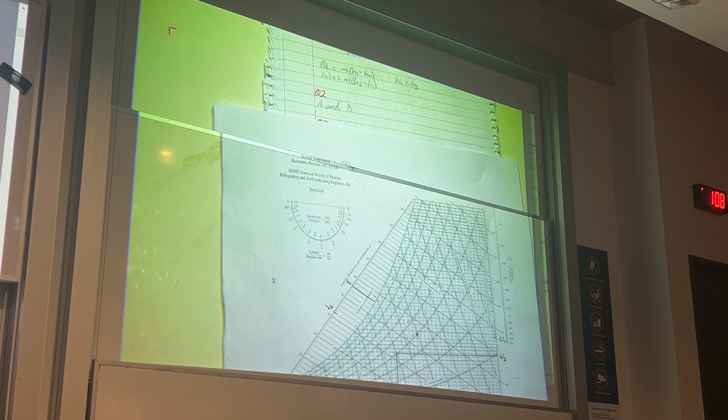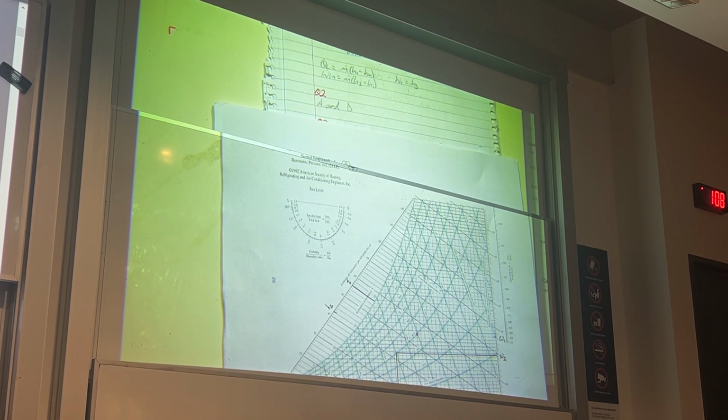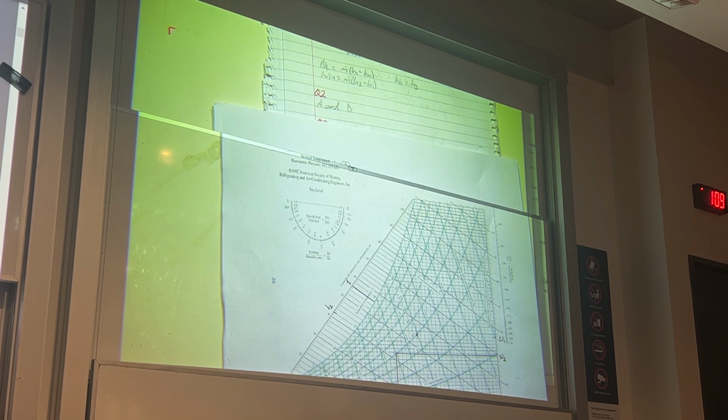Okay, so if you've had a read through, pretty much the first 2 are a couple, the second 2 are a couple, and the third 2 are a couple. So I'll take a look at the first 2 to start with. They're pretty much the inverse of each other. Statement A says for control volumes, the PV term added to the energy flowing in or out of the control volume represents an abbreviated form of the ideal gas law. And then B says for control volumes, the PV term added to energy flowing in or out of the control volume represents the flow work needed to push mass in or out of the control volume.